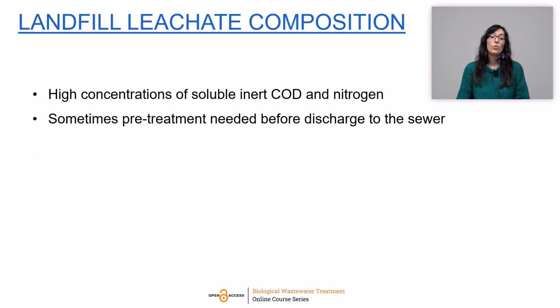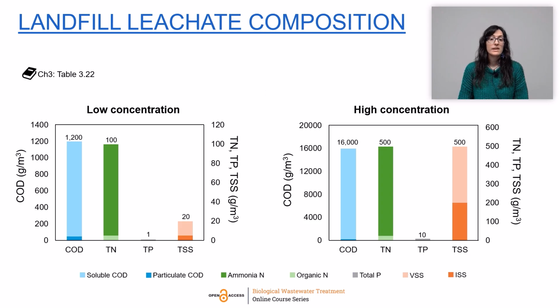Landfill leachate, the other external input, usually presents high concentrations of soluble inert COD, which is not removed in the plant and ends up in the effluent. And it can also contain high nitrogen concentrations, and sometimes a pretreatment is needed before it is discharged into the sewer. Here you have a couple of examples of the typical landfill leachate composition. You have one example corresponding to low wastewater concentrations and another one corresponding to high concentrations.